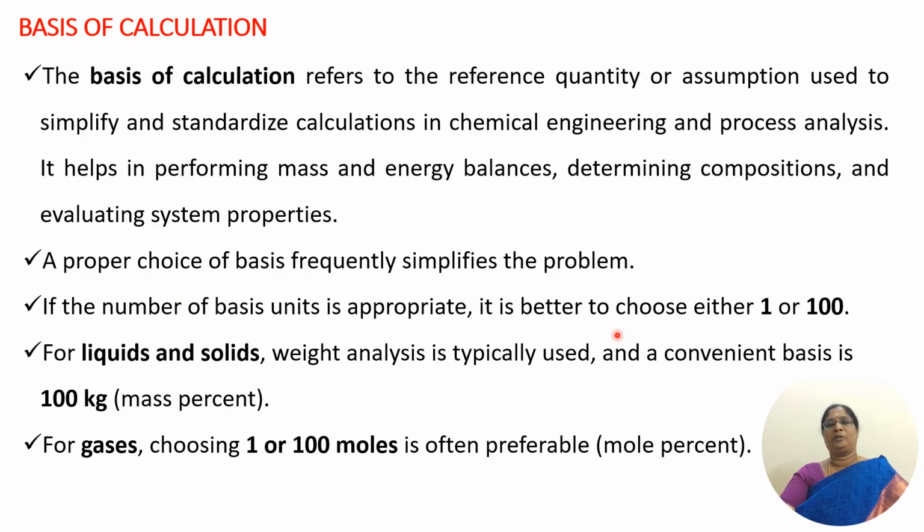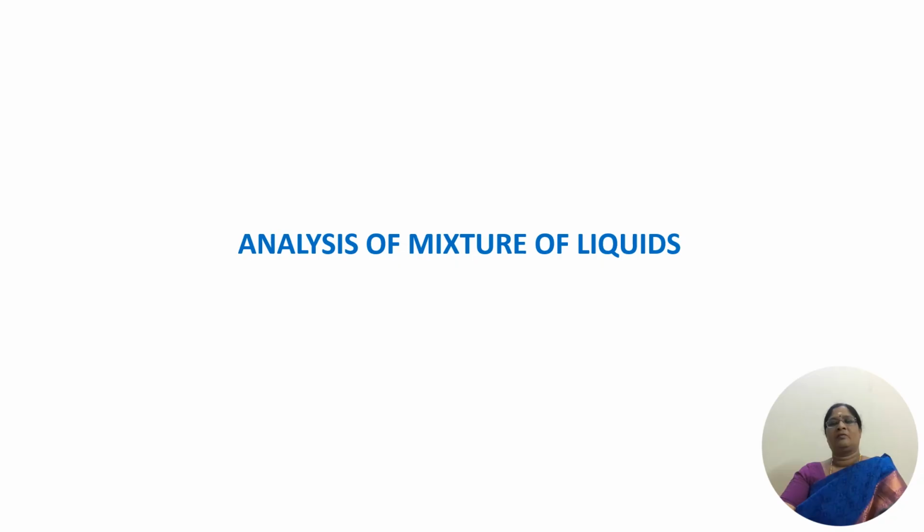Usually, it is better to choose either 1 or 100. For liquids and solids, weight analysis is typically used and it is convenient to take 100 kg as the basis. For gases, choosing 1 or 100 moles is often preferable, that is mole percent. First, let us discuss the analysis of a mixture of liquids and then go with the analysis of a mixture of gases.